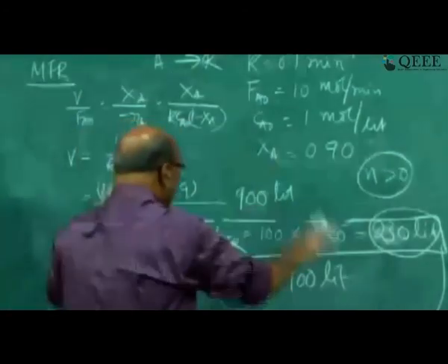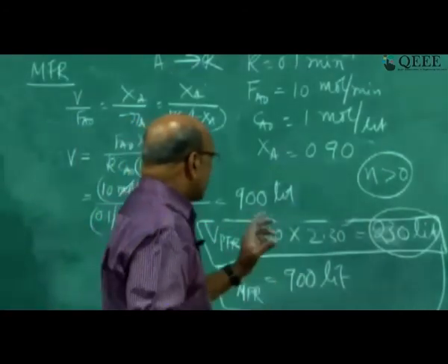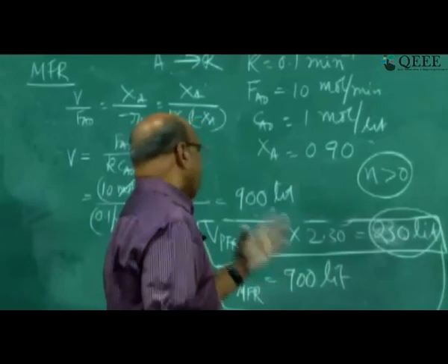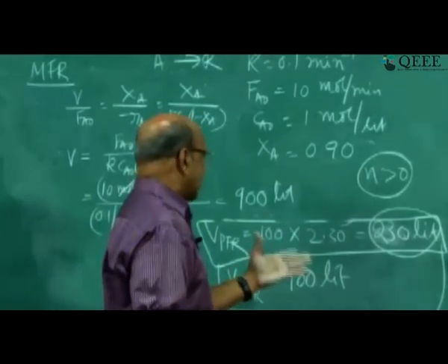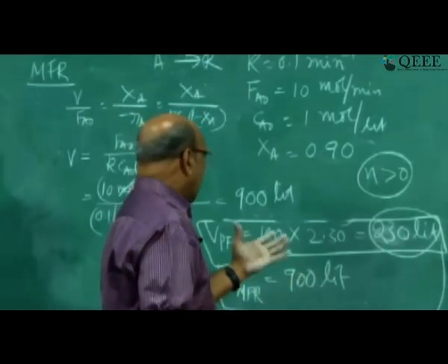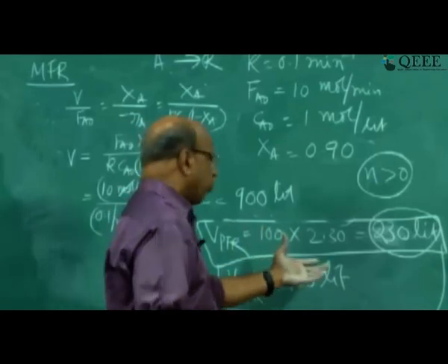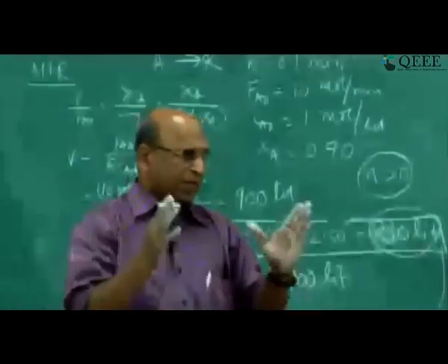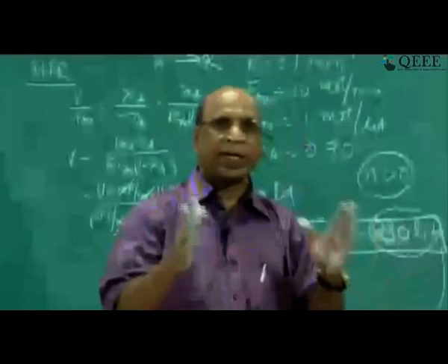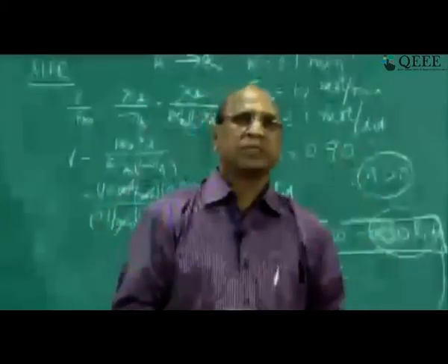So this is the problem I just want to tell you, so that I can support with calculations whatever I told, saying that plug flow is more efficient than mixed flow simply because of the assumption of every particle spending exactly the same time.